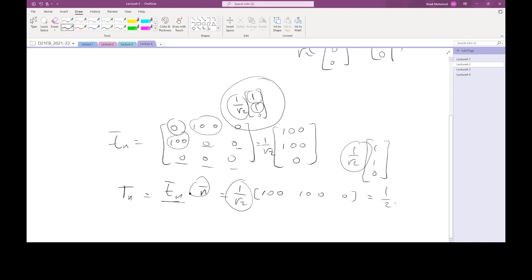This is going to be 1 over 2. And this is added to 1 multiplied by 100, added to 1 multiplied by 100. This is going to be 100 added to 100, added to 0. Or this is going to be basically 100 in its respective units, megapascal in this case. So the normal component on this plane is going to be 100.